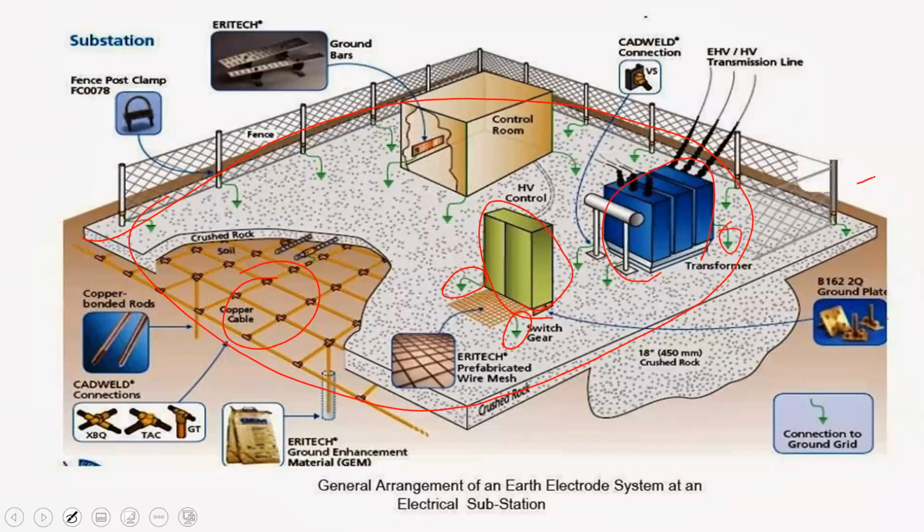All substations, and some of the things we just pass by, but my purpose here is to increase your sensitivity to a number of things, so you won't just pass them anymore. If you look, all substations are fully fenced, and it's not just to keep you from thieving the equipment, but the fence posts are all connected to the earthing mat.